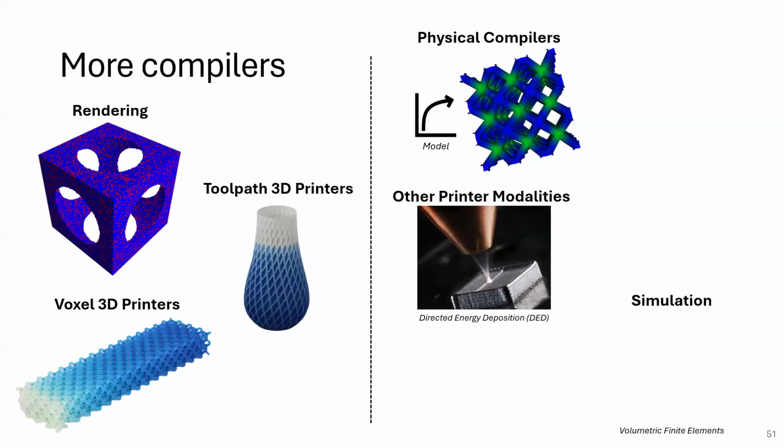So how do you get the powder there, and you shoot the laser, doesn't the powder dropping get in the way of the laser? So they have different techniques for dropping them down. They generally use these special recoaters that will go down and actually lay down the powders themselves. So usually they lay down a set of powder and then they'll come over top of it and laser, kind of as a one-two step. So they'll lay down powder, they'll laser back and forth rather than trying to hit them at the same exact time.